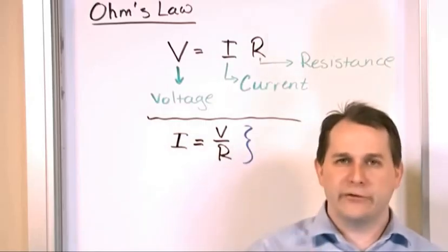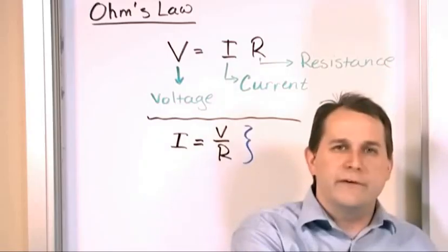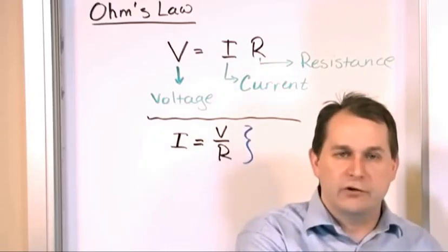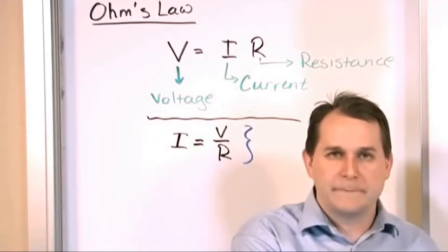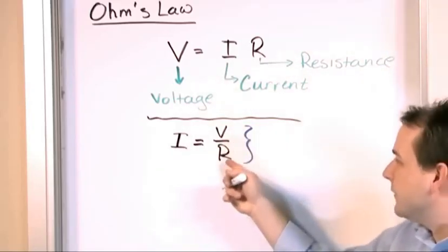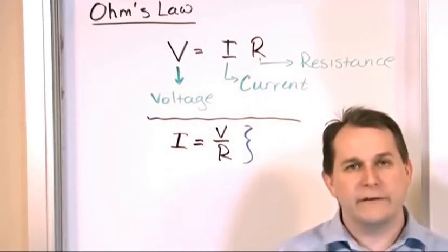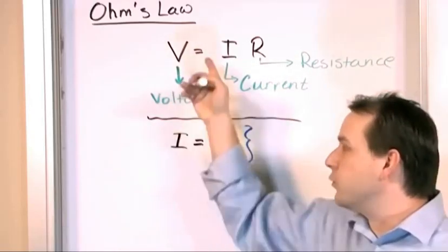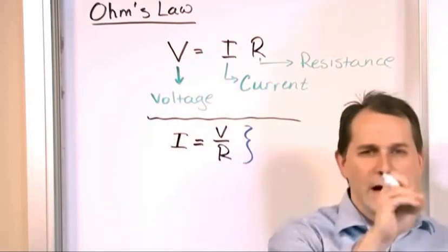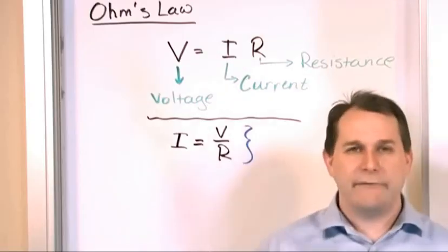At any point in the circuit, if you get a meter out and you put the little probes onto the circuit and measure the voltage across some object, right? Then this voltage divided by the resistance of the object, the resistor in this case, is going to tell you how many amps of current is flowing through that resistor. And this relation, whatever one you want to look at, it applies to every single object, every single resistor, and everything else in the circuit. It applies everywhere, all right?